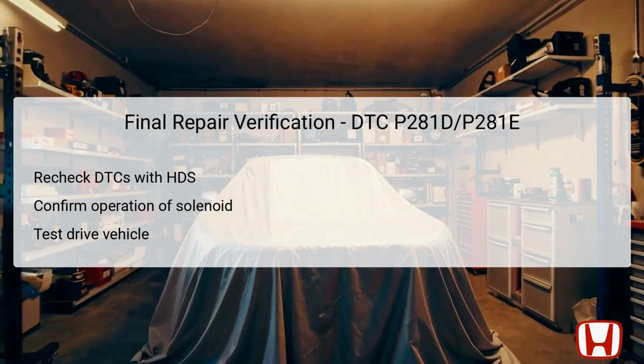After completing the necessary repairs, it is vital to conduct a final verification to ensure that the issues have been effectively resolved. Reconnect the HDS and check for any remaining or new DTCs. This process verifies whether the Shift Solenoid Valve OP is operating correctly after all adjustments have been made.